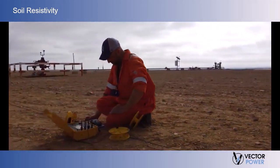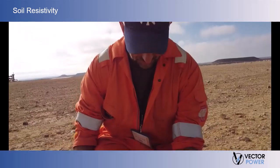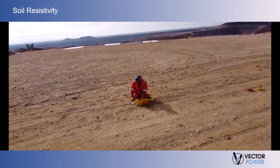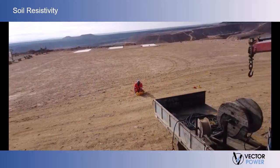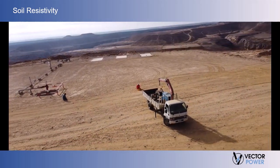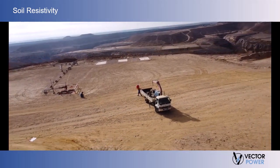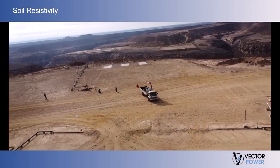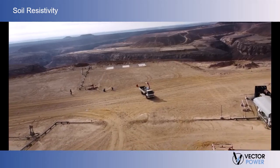Soils of ashes, shale, or loam tend to have the lowest soil resistivity. Soils of gravel, sand, or stone have the highest soil resistivity. As mentioned before, moisture content, temperature, and salt will affect soil resistivity.